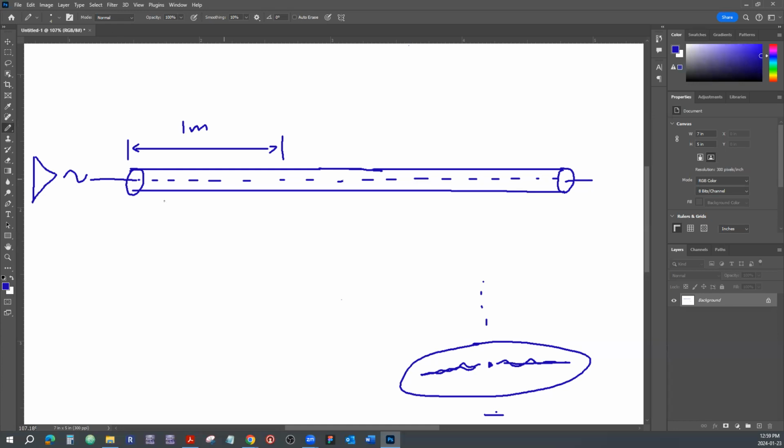That's what determines how hard the amplifier has to work to insert the wave into the cable, and the wave continues on its own. And if it inserts many waves, those many waves travel through the cable, but they travel on their own. So characteristic impedance is the impedance of the cable if the cable had just the first meter. That's what the amplifier cares about. So in this case, is the characteristic impedance going to change if the total length of the cable changes? Well, no, because it only cares about the first meter.